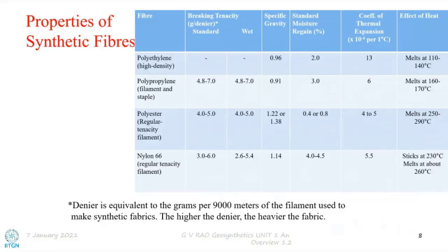Let us say if you want to use in flexible pavements, along with the top material like bituminous concrete or bituminous macadam, naturally you want to include them in this, probably we'll prefer polyester. Or at best, we'll also prefer PP, but not polyethylene because that is going to melt at the laying temperature of the bitumen mix. So we can't have it. Here it is definitely a higher melting point. Naturally, the choice of the polymer depends upon how we are going to use it also.